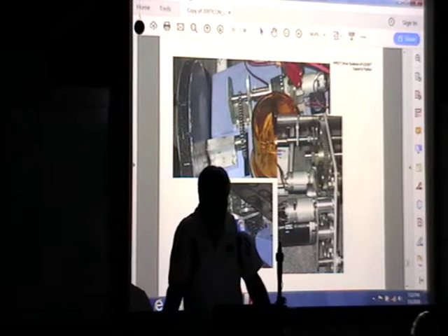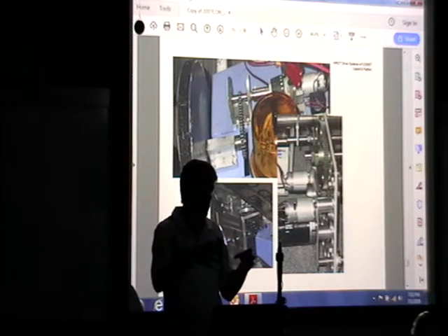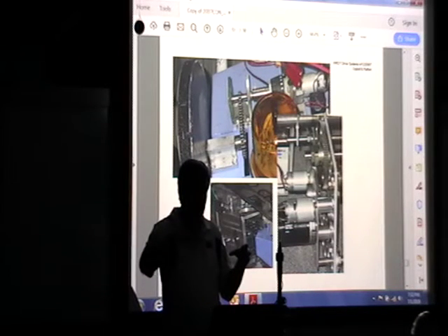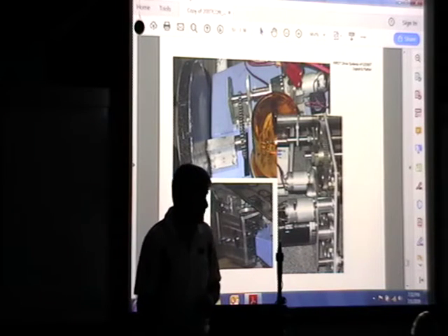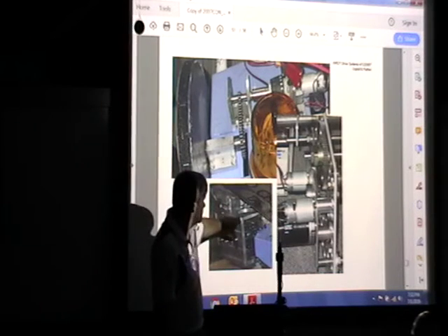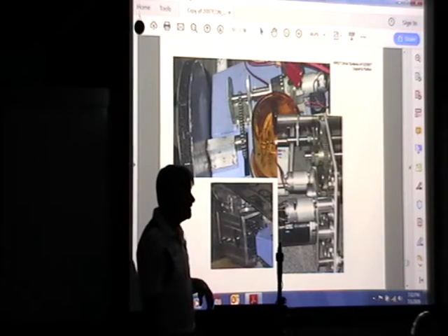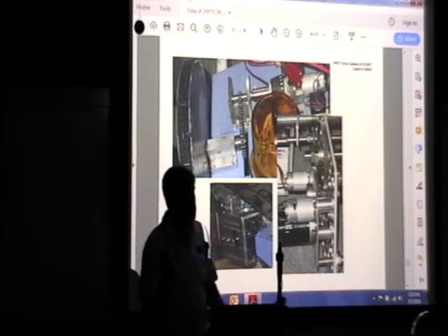And then you've got to look at, okay, well, my bearing's off a little bit in this laser part. How is that bearing going to get mated to my other bearing, which is out here somewhere? If that's on a piece of sheet metal that's doing this, there's no way those are going to be in alignment, right? So in this case, it looks to me like they've got machined surfaces here and here, so that's going to help keep things in alignment. Whereas if this was just a plain old piece of sheet metal that was bent up, you have a lot more trouble with that.